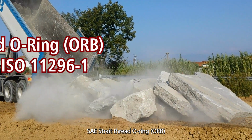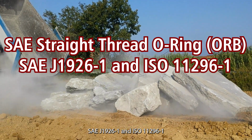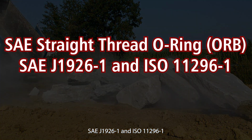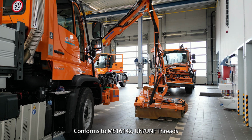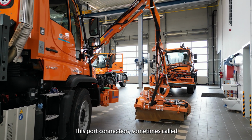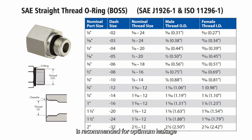SAE Straight Thread O-Ring, ORB, SAE J1926-1 and ISO 11296-1. Conforms to MS16142, UNF threads. This port connection, sometimes called O-Ring BOSS, is recommended for optimum leakage control in medium and high pressure hydraulic systems.